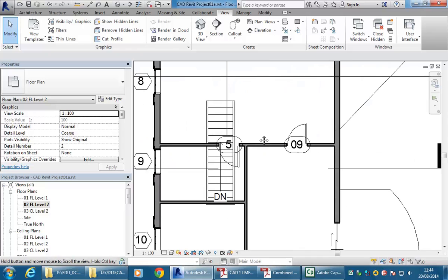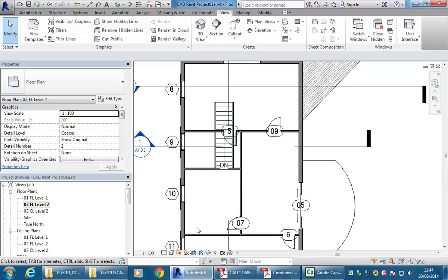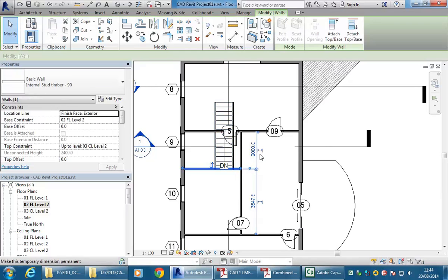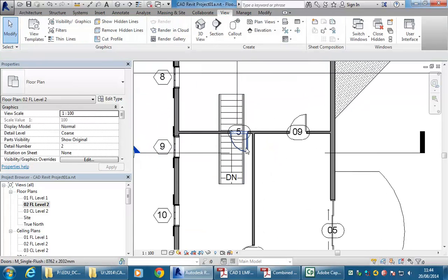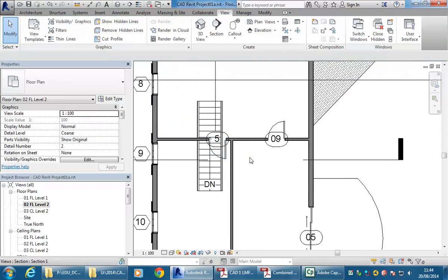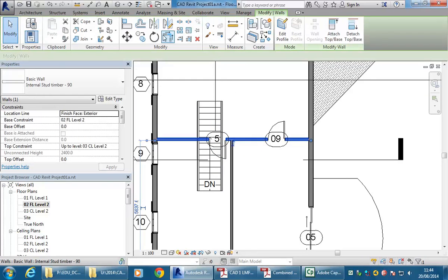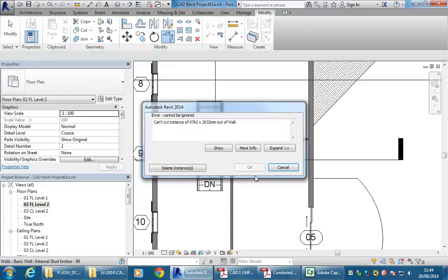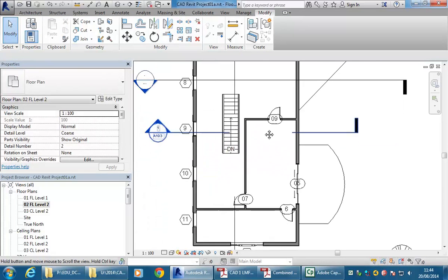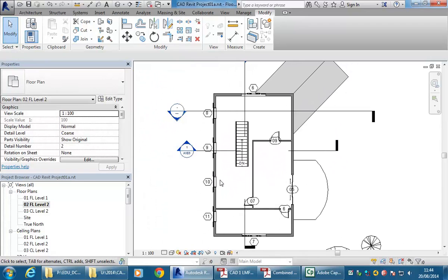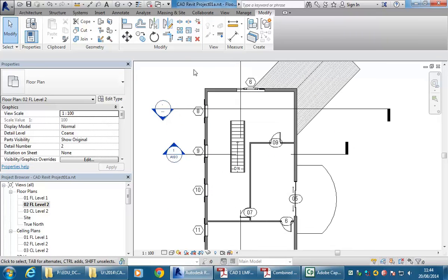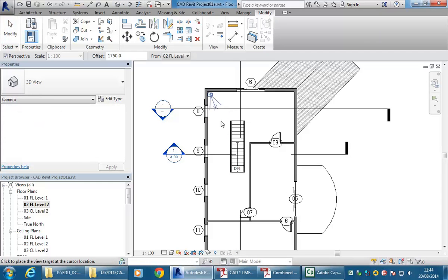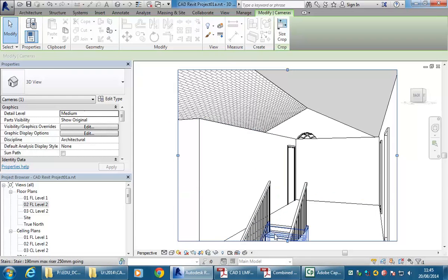And so there I can see now pretty clearly that my stair is going to go into this wall that I've put on the next level. So that's alright, I'll delete it, and I'll maybe change my layout a little bit. So these are some other things you can try. So using trim, we can make this a bit nicer so that I can see then the stair, and maybe I'll do a quick perspective there before I just look at railings as well. Okay, so we can see the stair now coming up into that level.